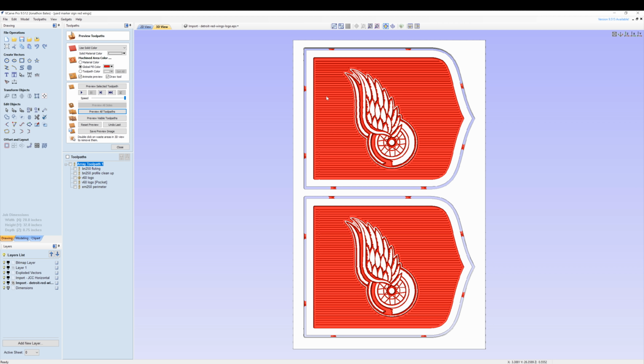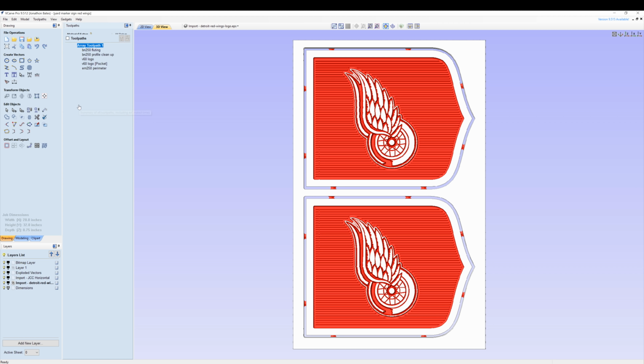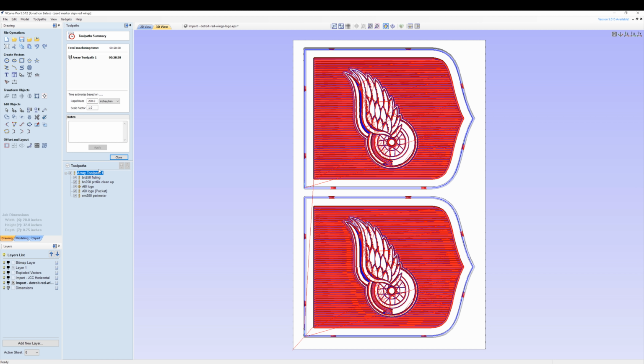Anyway, I thought that was interesting, especially using the fluting toolpath to give some texture that's much quicker than using the texture toolpath. And it just adds a little bit of visual interest instead of making it boring and plain with the flat pocket end mill. So let's press close and see what our final damage is on time. So instead of that one texture being 44 minutes and then an hour and a half, basically when you duplicate it, now I can cut both of these signs in 28 minutes with 3 different bits. That's pretty cool.